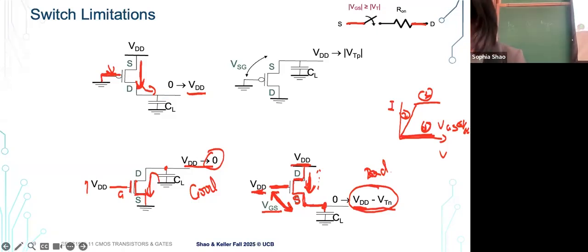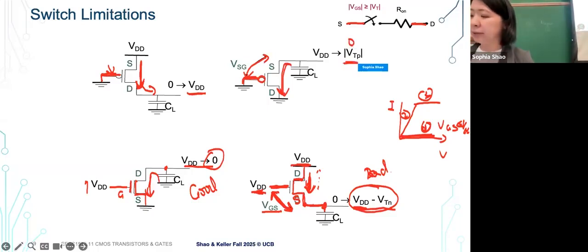But when we apply this as a discharge component, when we want to discharge the circuit, and we apply a 0 here, things are discharging again. There is a source and gate voltage difference. It will not get to a perfect 0. It will discharge to a very small threshold voltage here. So this will not get to a perfect 0 either.